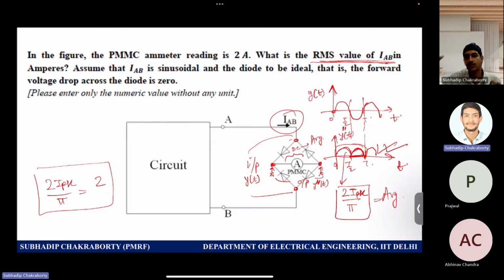So you have the positive lobes. And what is the RMS value of that? Either mode of sine or sine of t, RMS value. Both will be same, right? So what is it? It will be peak by root 2. So RMS of output full bridge rectified signal. So either you rectify full bridge and then take the RMS, or you take the RMS of the sine signal. Both will be same. Agreed or not?